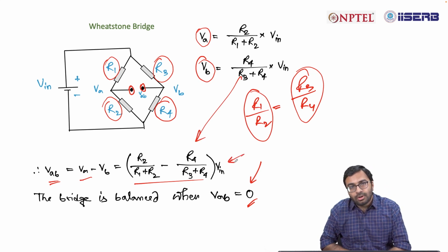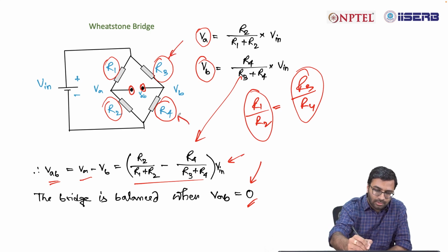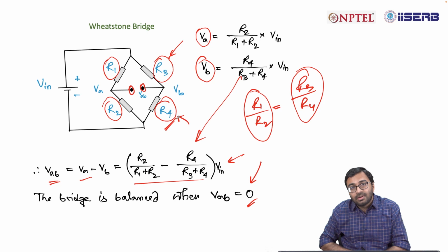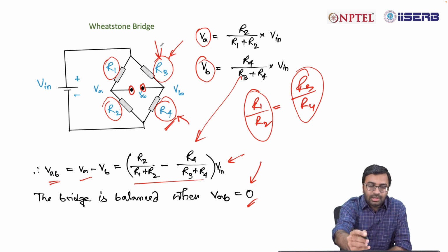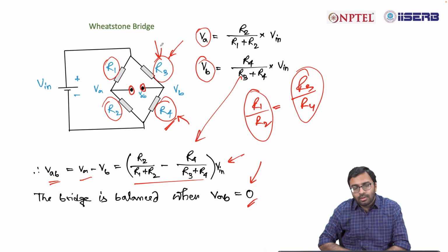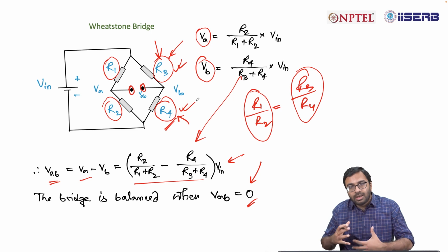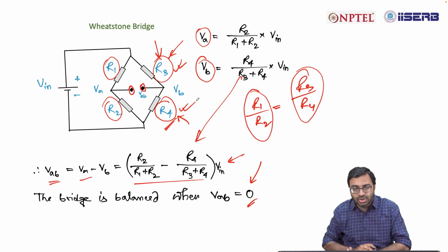Now, this circuit also can be used for sensor system design, where you can now replace 2 resistors with 2 sensors, and in this case, one sensor can act as a reference and other can act as a measuring device, or the combination of both will help to reduce the environmental effect. If there is any ambient change or change in the ambient condition, then this can be neglected using this type of arrangements.